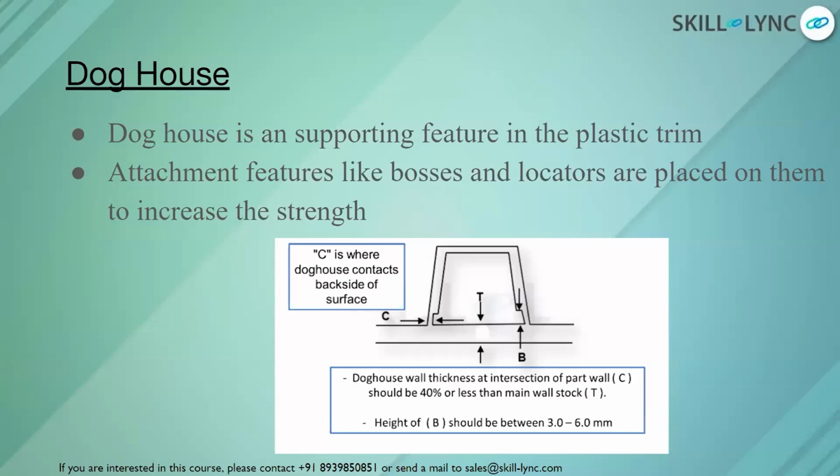To make sure that that is avoided, we are going to neck or reduce the thickness at that particular area. That way the amount of molten material flowing to that area is reduced, or the pressure and the speed at which the molten material goes to it is reduced, so that there is uniform flow in the horizontal direction as well.